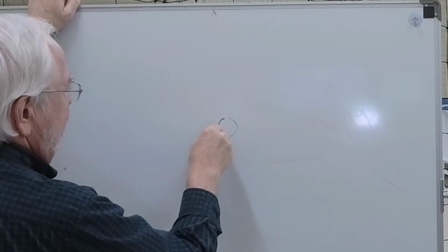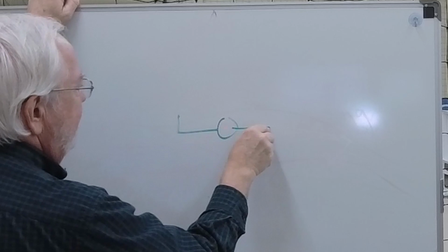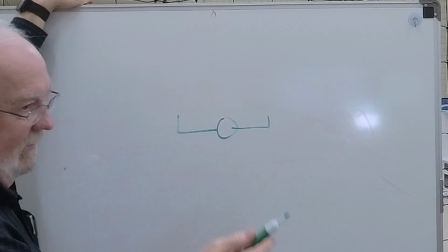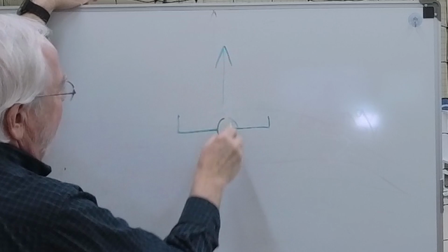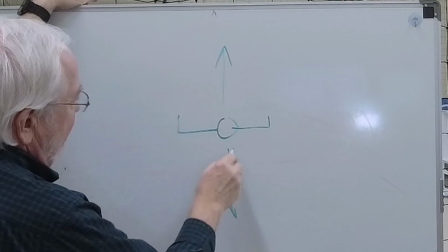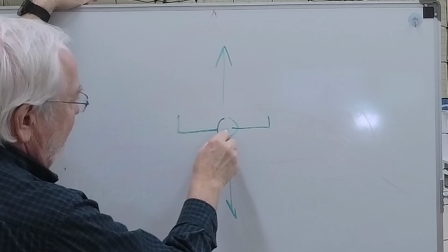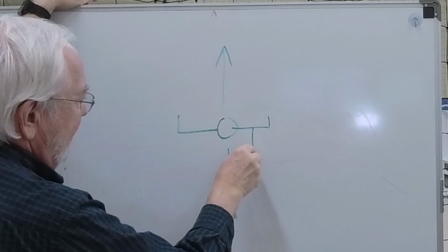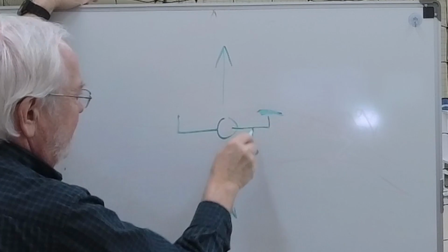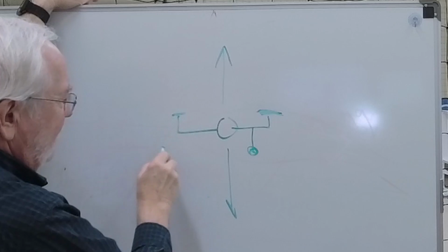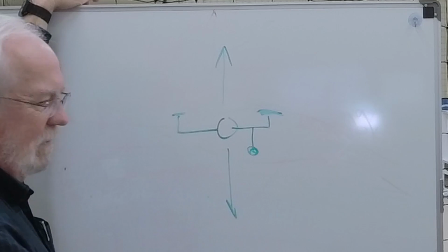Remember, center of gravity is simply, again, my little picture of the drone, looking from the back end. You could look at it which way you want to, it doesn't matter to me. But we have lift here, we have gravity here, but the gravity is going to act off the center of gravity. So if you have a big old weight hanging off the wing here, this propeller blade is going to have to work really hard to balance this one here, or hardly turn at all. And so it's going to be less stable.